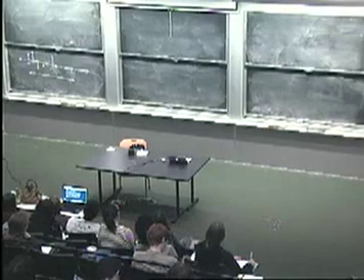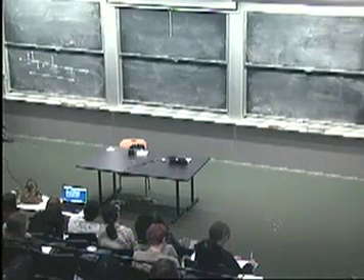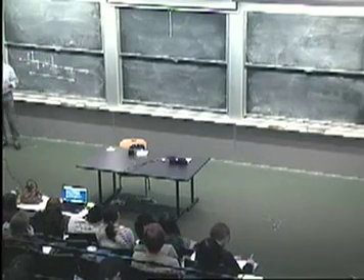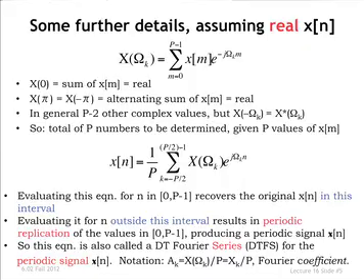Okay, so what you're guaranteed is that if you apply that formula, you will recover every signal value in this window of length capital P. But what happens outside of that window? Well, if you look at this expression, is the right-hand side here periodic? You should suspect that it is because of the e to the j something in there.